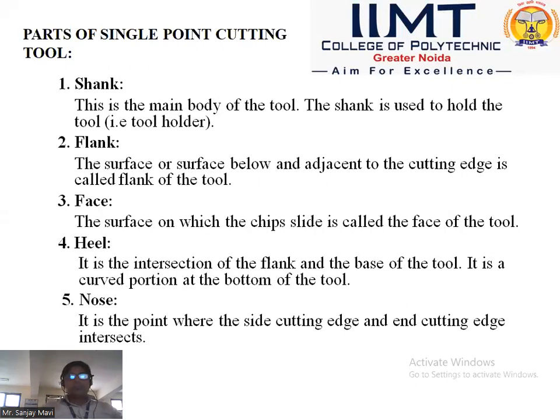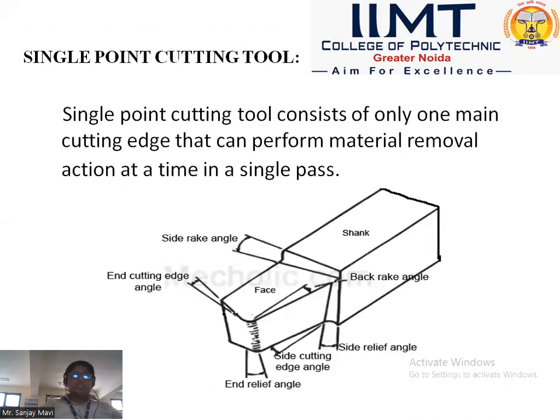Face. Face is the surface on which the chips slide. In this figure, we can see here, this is the face. During the cutting operation, this cutting edge or side cutting edge cuts the material from the workpiece, and the shear of material which is removed from the surface of the workpiece slides on this face.